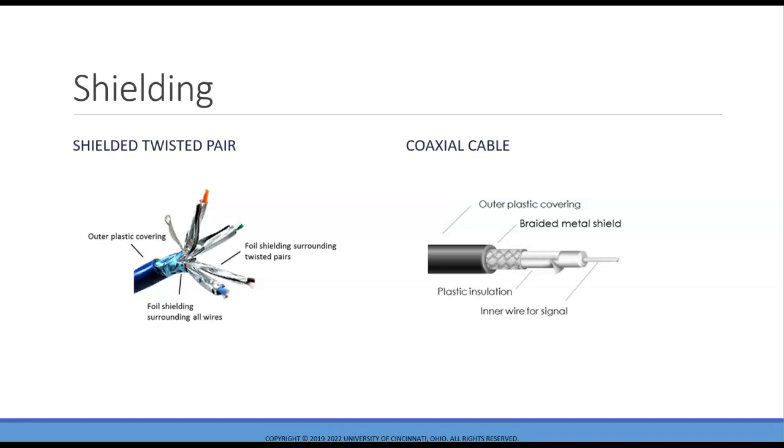Coax uses a braided wire instead of a solid metal shield to keep coaxial cable flexible, but the heavy shield does not make coaxial cable less flexible than twisted pair wiring. Variations of shielding provide a compromise. The cable is more flexible, but has slightly less immunity to electrical noise.